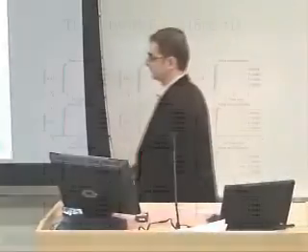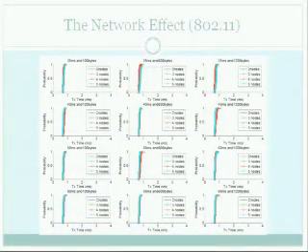Now, we tested several network parameters that had to do with the number of nodes, the transmission period at which we were sending the packets, and the actual size of the packets. So small packets, medium-sized packets, and large packets. Now, at every experiment, one sensor node was directly interfaced to a data acquisition card, and we recorded detailed information about the power and time. What you can see here is the empirical cumulative distribution function of the single packet transmission time in the case of the 802.11 radio when this is driven by the MSP430 processor.